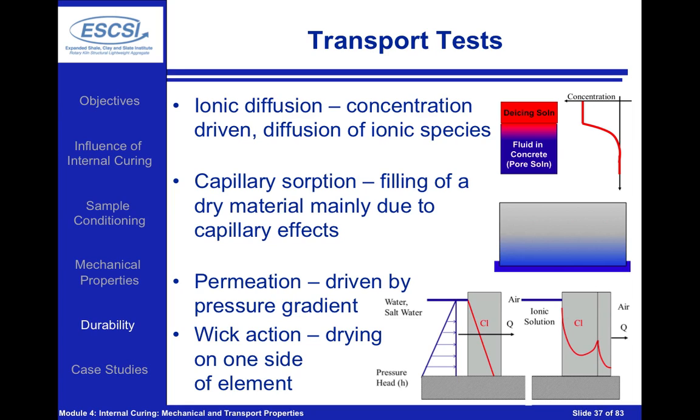Permeation is the next one, where we're really driving water in by a pressure gradient, and wicking is where we're essentially having a combination of diffusion and absorption and then a drying out on the other side of our concrete. By the drying effect, we're evaporating water off of our concrete, but we're leaving salts or ionic species behind, and they can actually create a higher concentration right behind that drying front inside of the system.